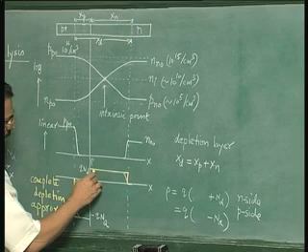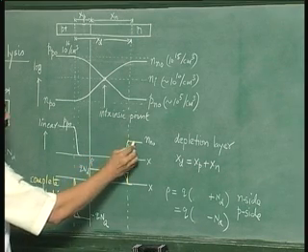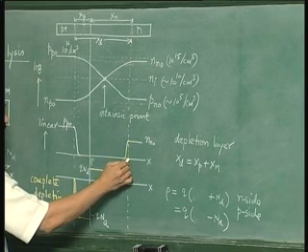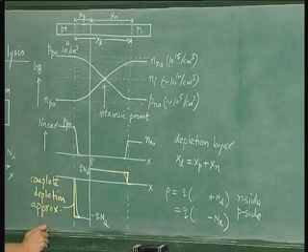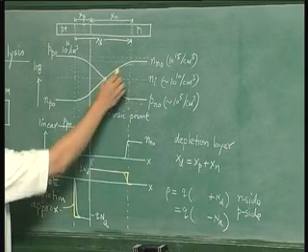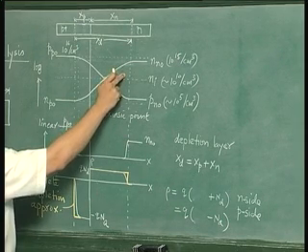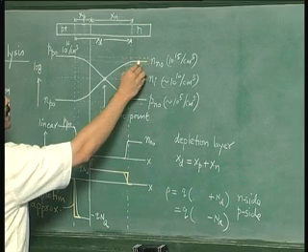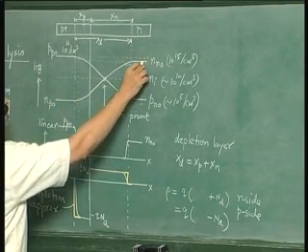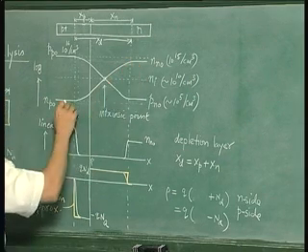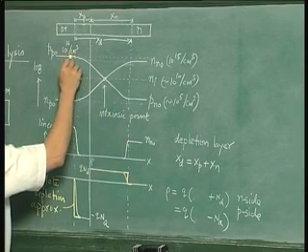Now please note, assumption of a space charge picture like this is equivalent to assuming that the electron concentration changes abruptly at this point to 0, and hole concentration changes abruptly at this point, which is obviously not true, because if I were to show the complete depletion approximation on a log scale, then it would mean that I must assume electron concentration n changes from Nn0 to Np0 abruptly here, something like this, and Pp0 also changes abruptly.